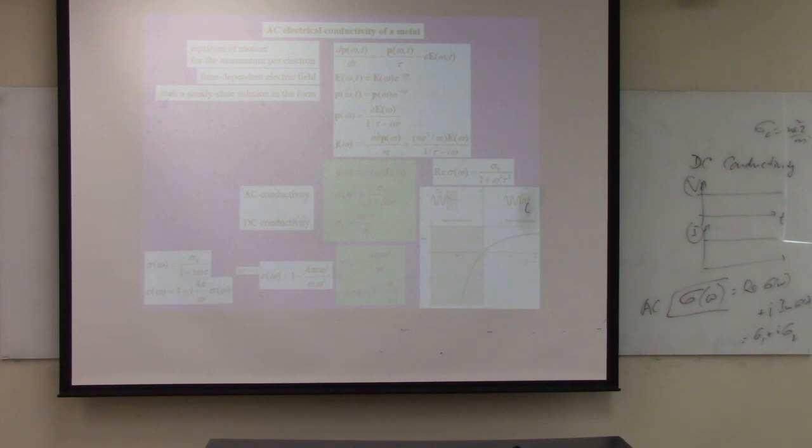Basically charge is given by this distance x times n times e, that is the charge, right? Charge times length L is the dipole moment, divided by volume. Volume is A times L. A and L cancel, this is basically e n times x. So please remember, your polarization is given by e n x, and I can write P divided by epsilon 0 E.